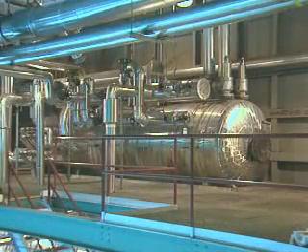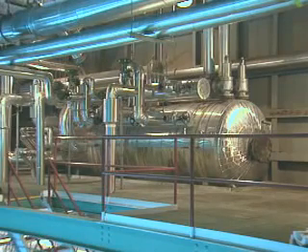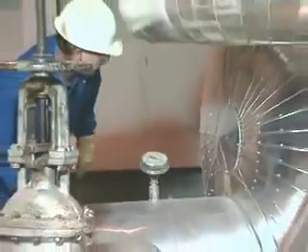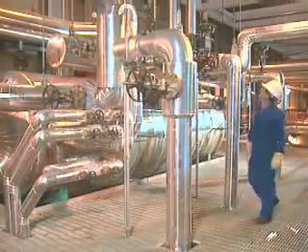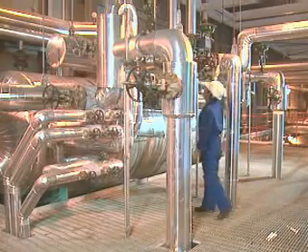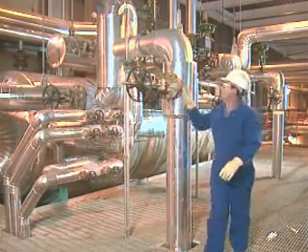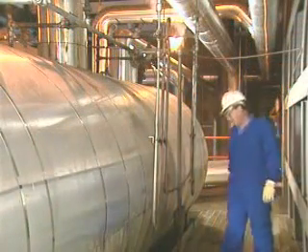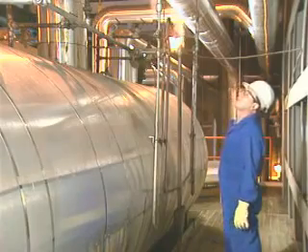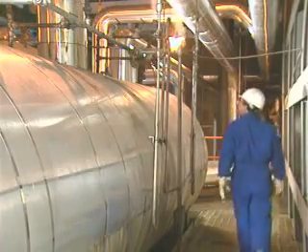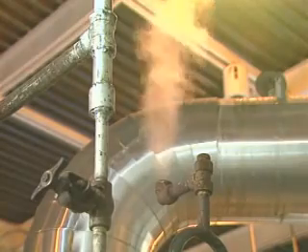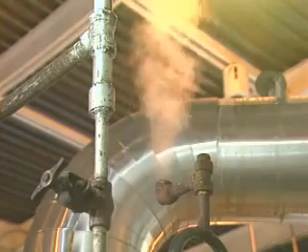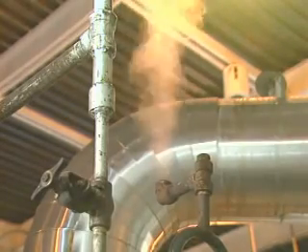Monitoring the performance of the deaerator is important for maintaining overall system and plant efficiency. Check the appropriate gauges for the proper extraction steam temperature and pressure. Look for any signs of leakage and make sure that all the valves for the deaerator are in the proper positions. Watch for excess venting from the deaerator. That can cause a major loss of heat energy and fluid from the deaerator, which will decrease plant efficiency. Also watch for insufficient venting. That will allow oxygen and other gases to remain in the condensate and feed water system and cause problems downstream.